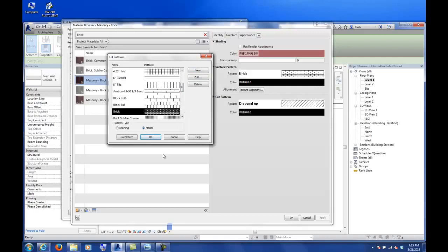So when I scale my drawing up and down, it's still going to be an 8-inch wide brick by 2 1/4 inch high brick pattern. That brick pattern is never going to scale as far as changing the actual true scale of it. I could actually strike a dimension or scale it with a scale when it prints out, and it'll scale off as 2 1/4 by 8 inches. So that's kind of the difference between those. So you just kind of have to pick and choose what you want.